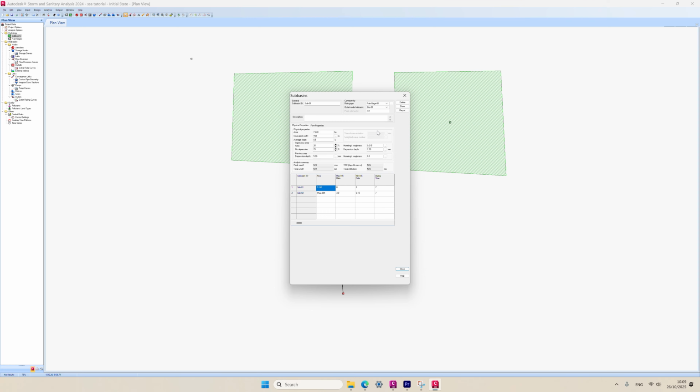So right now our total area is 7.24 hectares. 7.24 divided by 3, so 2.41. And the sub-basin 2 we created, let's make it 2.41 hectares, and that's minus 2.41 from the whole area, so that will be 7.24 minus 2.41, so that will be 4.83.